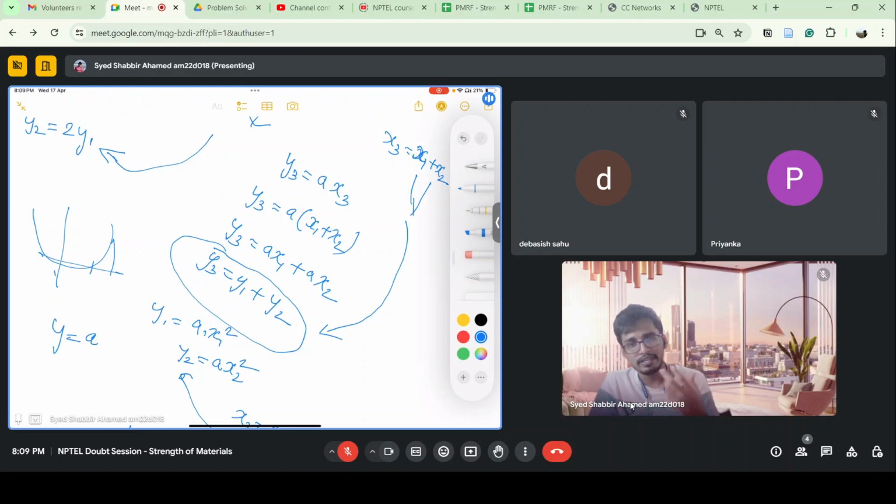If you have a material which is experiencing different loads, you can get the principal stresses, and using those principal stresses and these theories of failure, which come with some expressions, we can see whether the stresses coming in the structure are within the permissible limits according to the theory, which may be maximum principal stress theory, or Tresca yield criteria, or maximum shear stress theory, or Mohr-Coulomb theory. These are divided into different theories depending upon the material, and also depending upon the development at various stages.